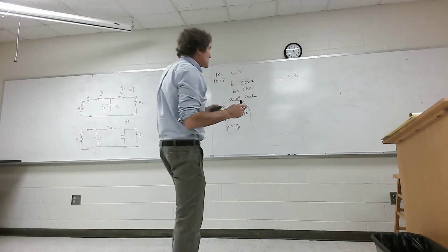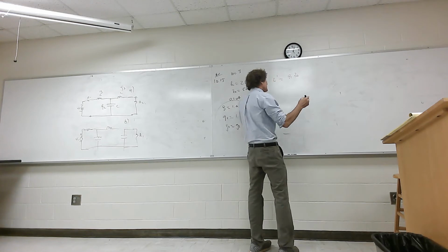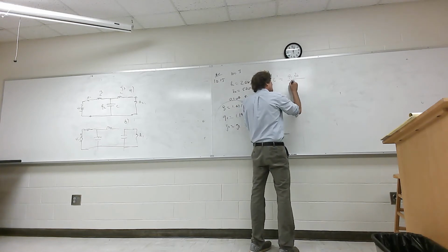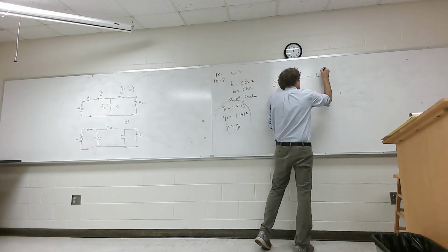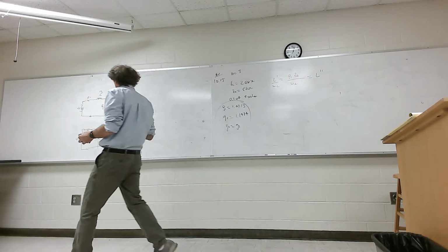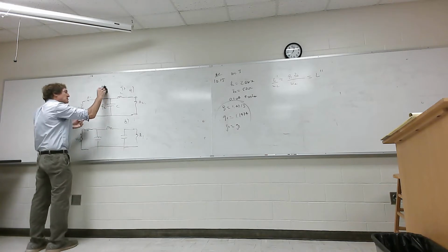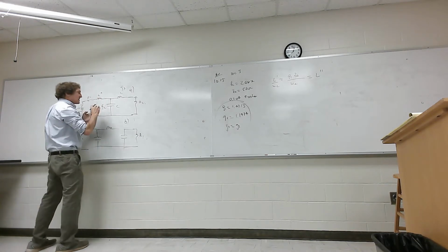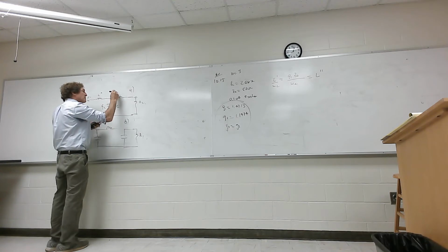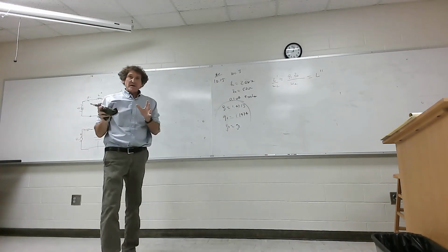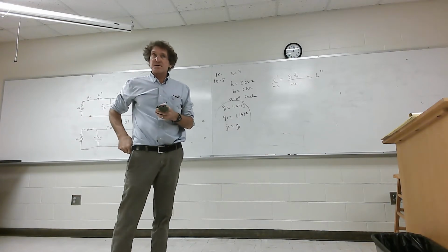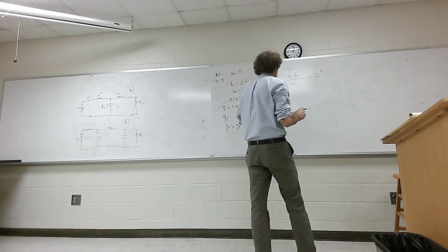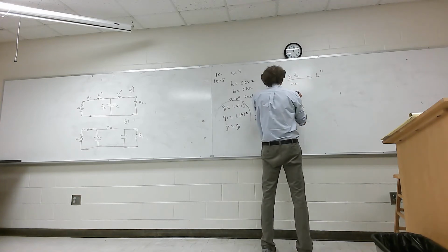Then if we want the actual value of that inductor, we take this and divide it by omega C. So if we divide this by omega C, now we get L double prime. That would be over here, this would now be L double prime. It'd be the same thing over here. Do y'all follow me on this? This is just a simple method. It doesn't go through the science of why it works. It's just showing you this is the way we do it. So for this value, the L double prime, we have G1 here is 1.0315.